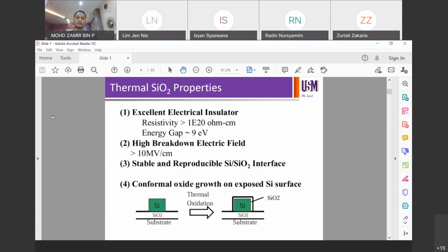the oxide is very thin, you might be encountering problems particularly at the edge of the square, at the corner. It's going to be a bit challenging to get conformal there, and also to have your silicon oxide integrity at the edges there.